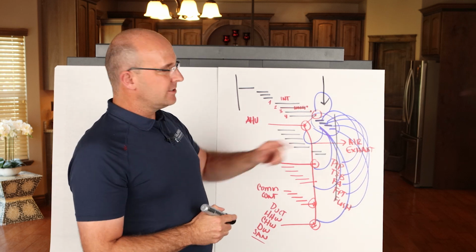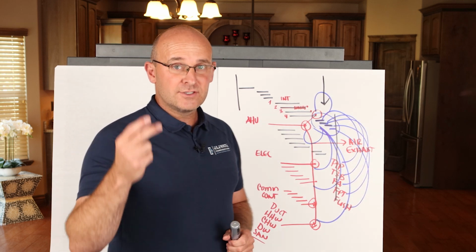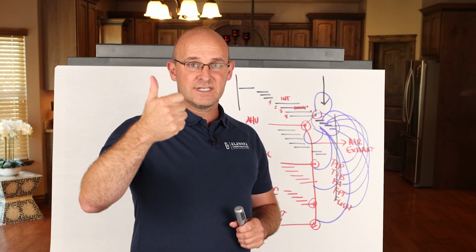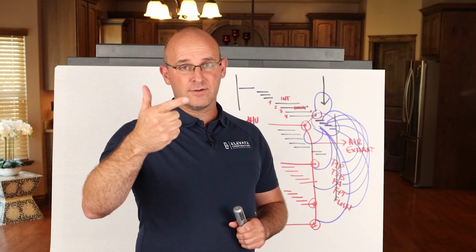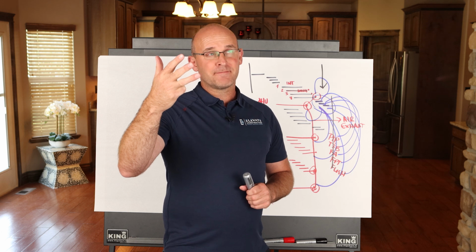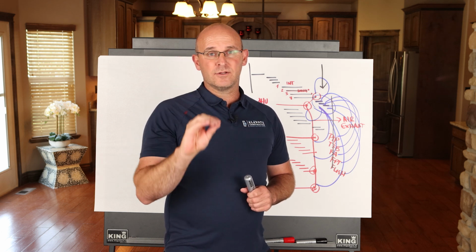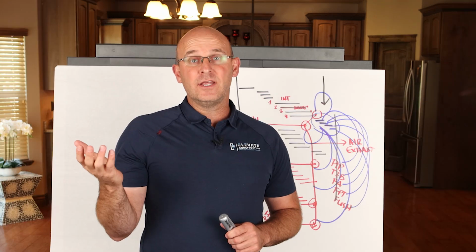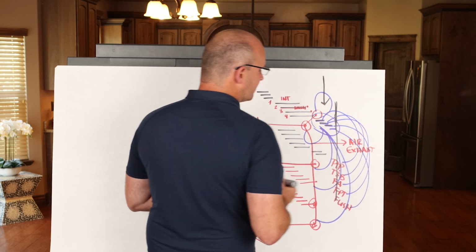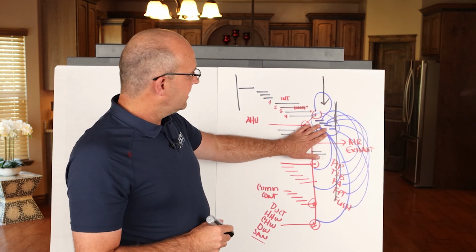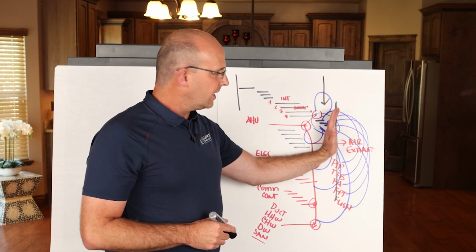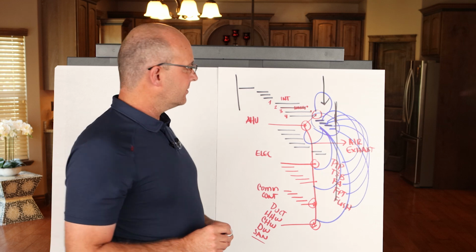But one of the things that I would say is that understanding this piece is crucial, right? Typically for substantial completion at the end, you're going to need to finish, have your inspections done, engineering walk. You're going to have your elevators, your life safety, all of your fire sprinklers up and running 100%. You're going to have a punch list, a preliminary balancing report, and any of the sign-offs by the local authority having jurisdiction, and then you can receive your substantial completion. Knowing exactly what the substantial completion requirements are is crucial in this phase, because you need to network this. This is one of the most important pull plans you'll do on your project, so you know how you can finish. And like I said, all of those things are included in there.